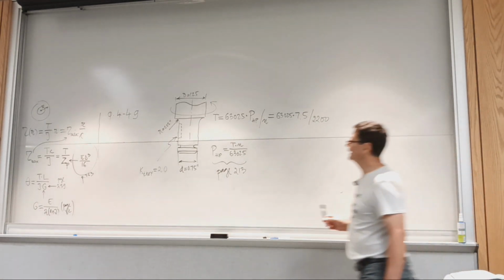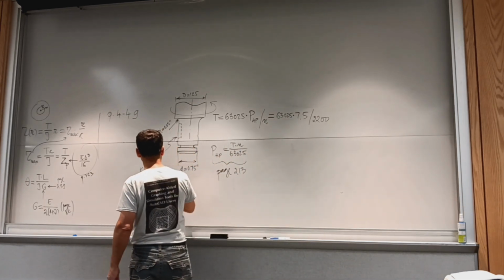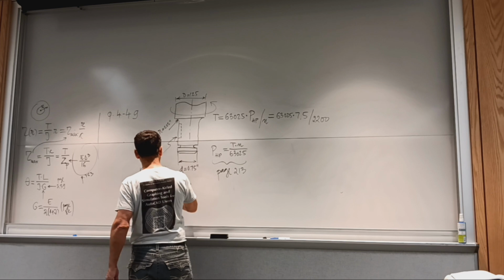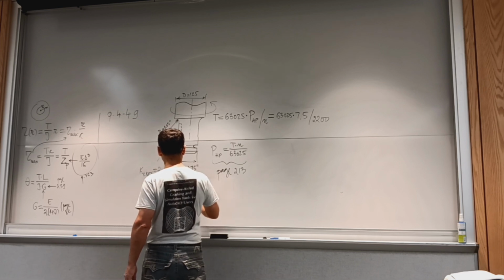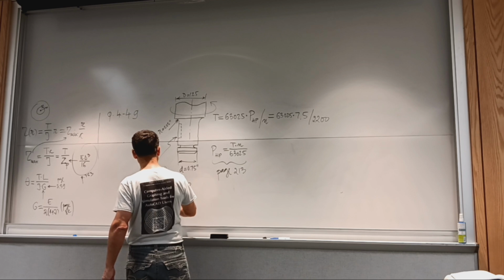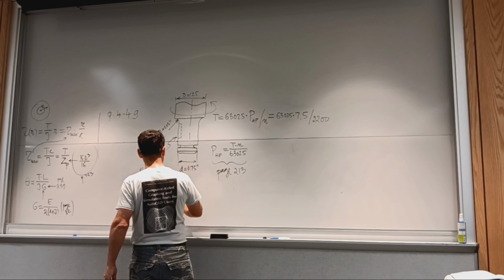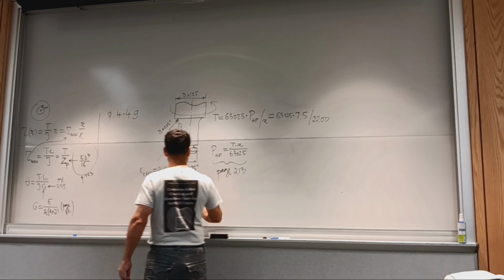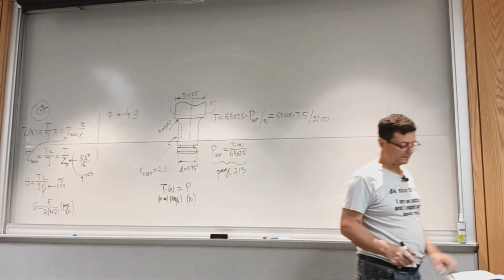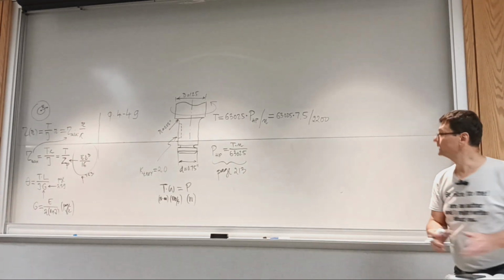If it's in metric, that's easy. So in metric, torque times omega is power. Torque in Newton meters, radians per second. Power, it will be in watt. So Newton meters, radians per second, and power in watts. Right? Okay, so we can now calculate the torque,